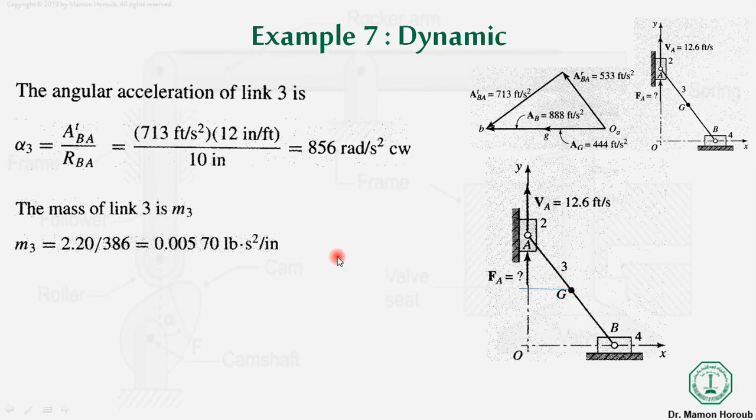So this moment can be cancelled when we apply the inertial force at a certain distance, with a moment arm of h from the gravitational center. The inertial force ma multiplied by h creates a moment that neutralizes, or becomes equal and opposite to, the moment created at the center of gravity due to this body. So from here we can find h.